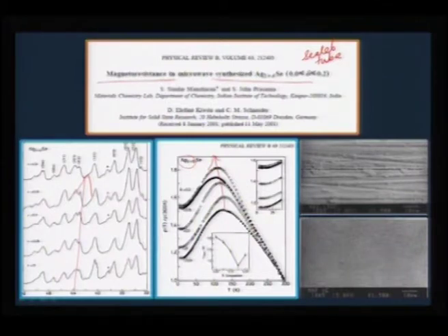The insulator to metal transition is noted in silver selenide compounds, and one important point is when we take silver and selenium, mix it, make cylindrical compacts, put them in a sealed tube and expose it, there will be very bright flashes coming in this vessel, which will not only yield silver selenide formation, but will also densify the compact.